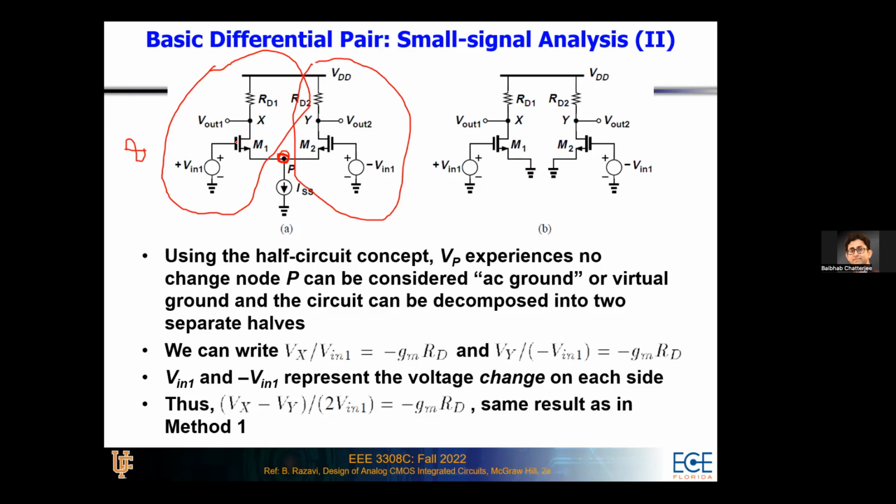So it will be exactly the same signal that you apply at the gate. On the other hand, on the other input, you apply a differential version of the previous input. So the M2 transistor will result in another source follower operation. So at the source of M2, you will see exactly the same as what you have applied at the gate of M2.